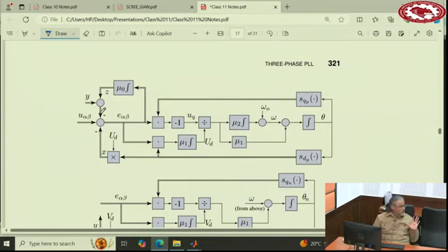Remember, zero sequence doesn't matter, because whether it exists or doesn't exist, it will not come to alpha beta. So we don't worry about zero sequence. But we worry about DC because practically, as we explained before, it may be generated during the signal conditioning and processing stage, even if the original signal doesn't have DC.